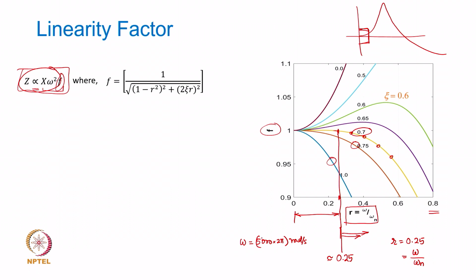I am saying that from my gearbox, the vibration frequency expected of interest is 5000 hertz. Okay. Now, for that to measure 5000, I am going to use cycles per second as the frequency, because omega n is also going to be then in terms of hertz, okay, because the units are consistent now.